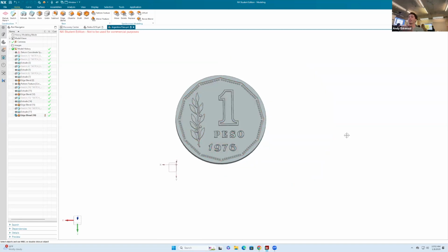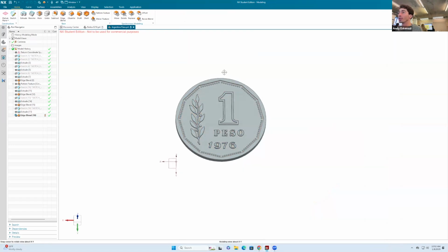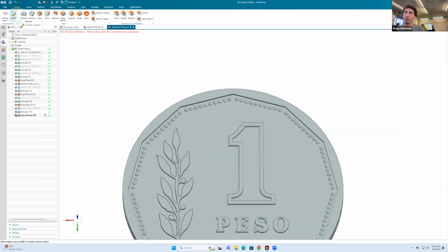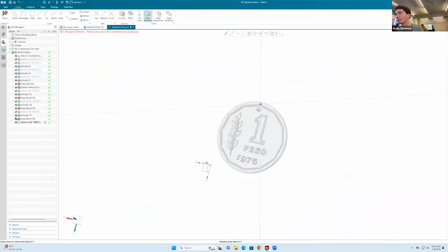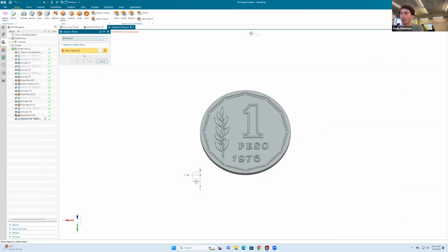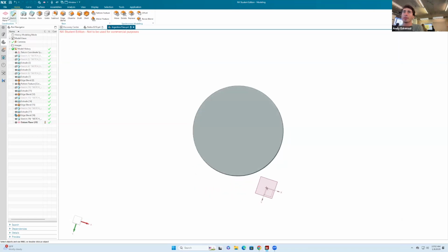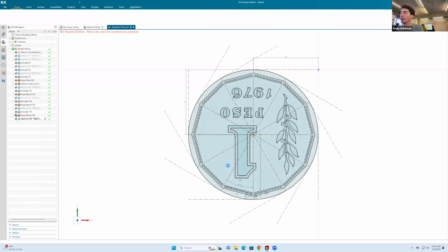And now just one last detail that is not part of the coin, but you can actually see it has a little bit of a pattern around the edges. So let's give that as well in here, because I think it's gonna make it look even nicer. So I'll go here to sketch. Actually, this might be better if I do it on the original sketch. Actually, you know what? I don't want that plane. I can just delete it. I'm gonna go back to our original sketch, edit.